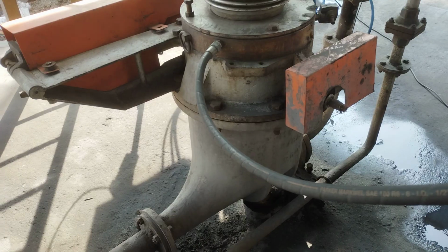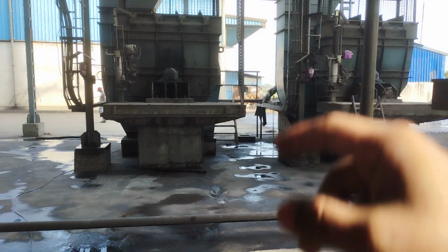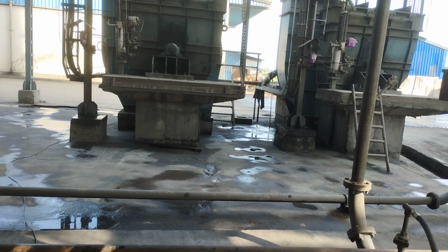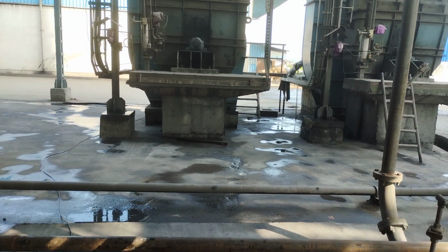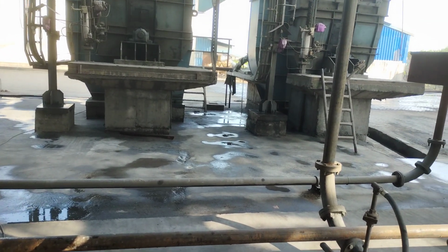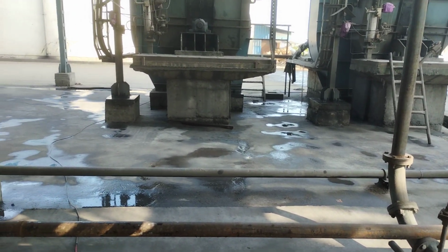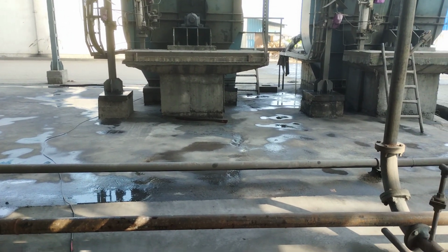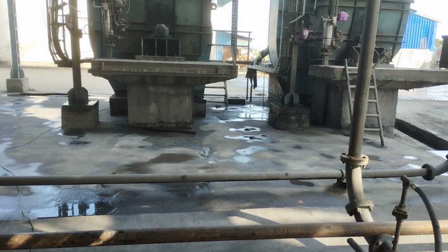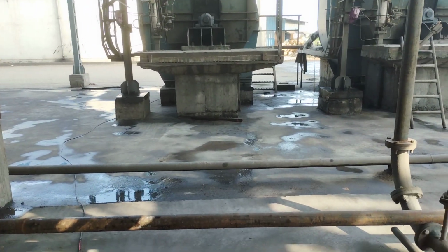Two FD fans. This is FD fan damper 1 and 2, for air inlet, operated by I2P with a feedback switch for open and close. The I2P is very important for the opening percentage, or a smart positioner is needed for the opening percentage. The FD fan discharge goes to every header and the air preheater to heat the air and release moisture from the air for good combustion of the fuel.